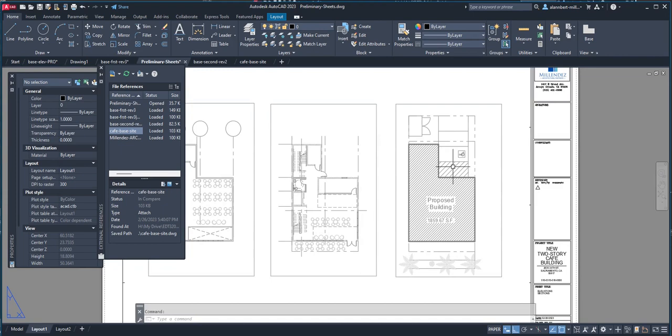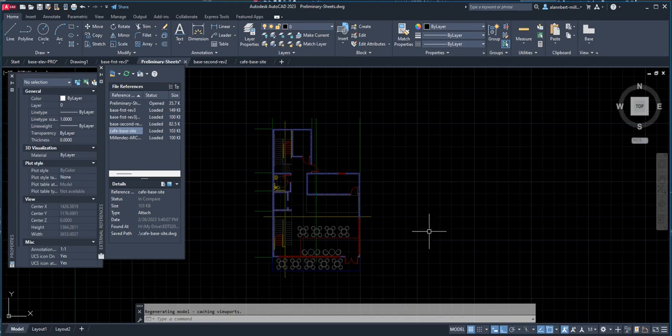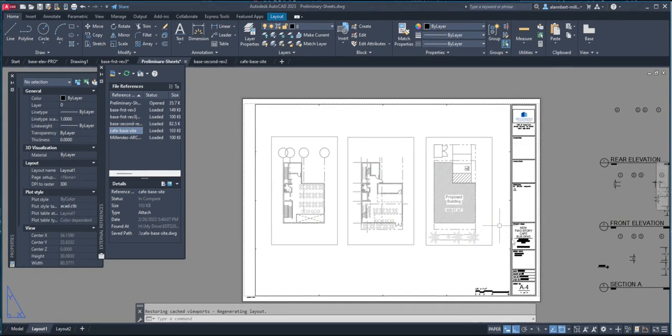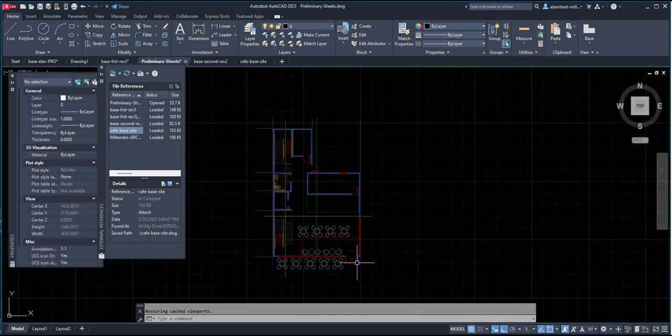Also, the LT scale, you might want to change the LT scale. So on your model, what is LT scale? Oh, it's one. And then on the layout, you simply have to change again the LT scale with the three LT scale numbers. The three LT scale numbers: in the model space, we already checked our LT scale here, right? LT scale, and it's one.